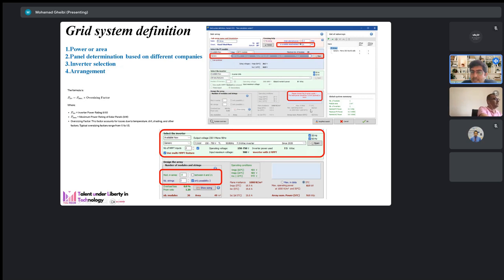Okay, here in each simulation you will have an error if the photovoltaic panels and your inverter are not paired together, and you should change them with trial and error. Based on my experience, I'm telling you, in my opinion, first, based on the local market conditions that you have, set the panels that you want to use, and then in the next step, based on trial and error, find the inverter, because there is more variety of inverters available in the market in comparison with the panels.